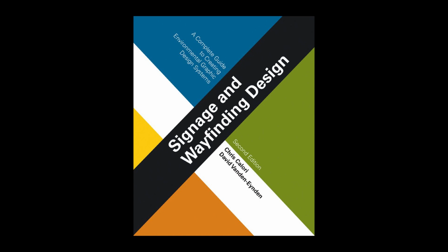Each kind of submittal provides a different piece of information about the sign program's fabrication. Shop drawings indicate how the fabricator will construct and install the signs. Artwork shows the size and layout of graphics for each unique message/sign type combination within the sign program. Material/color/finish samples show the actual materials, colors, and finishes the fabricator will be using on the signs.